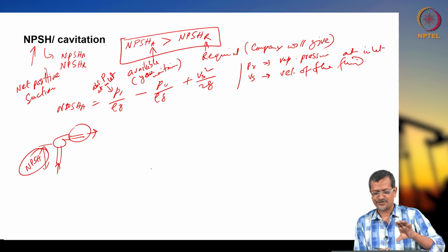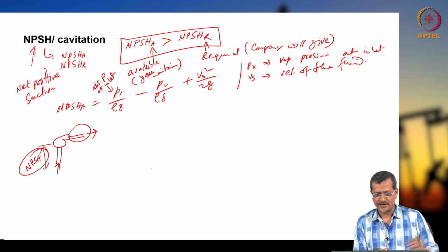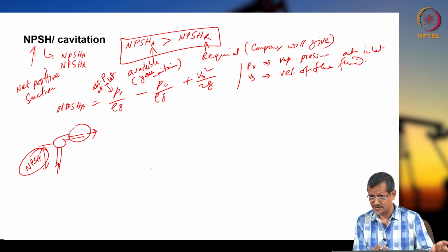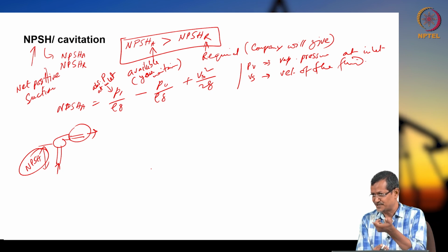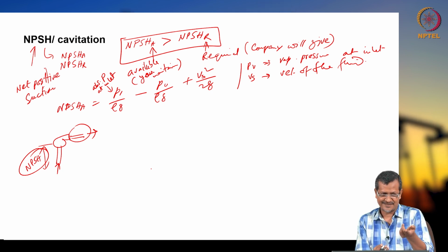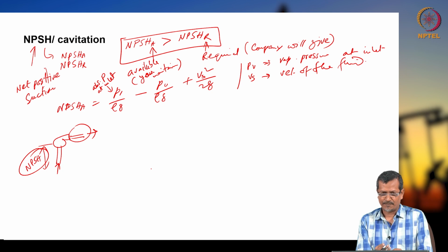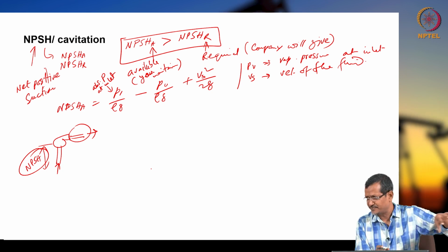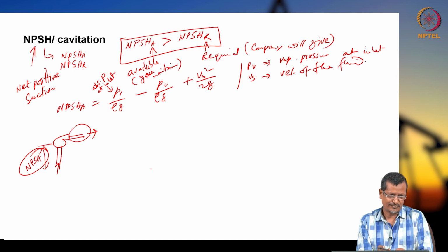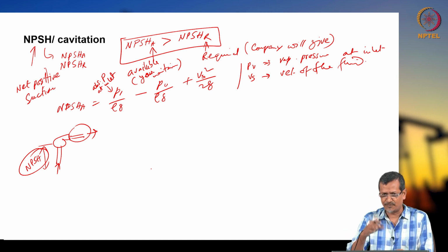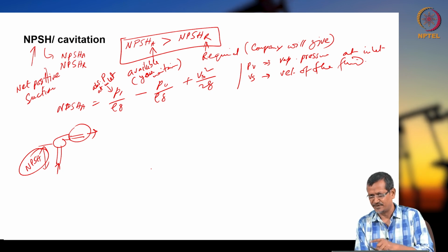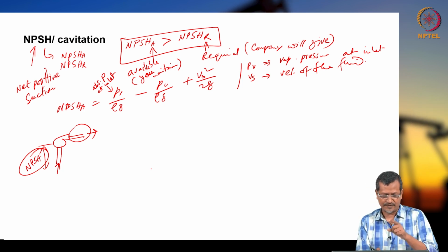So when you check whether NPSH is available or not, you have to check fluid temperature and fluid property. Instead of water, if you are using, let's say, petrol, your vapor pressure and boiling point change, which means it will not work. Then you have to check your pipe diameter, any sharp bends, and long pipes. All the parameters which give pressure drop or vapor pressure change must be checked. If you are not checking, your NPSH will have problems, and that will give you cavitation.